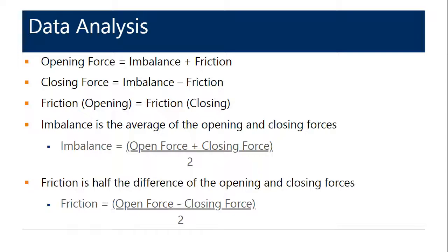Typically, there are other trunnion bascule bridges that have rolling element bearings that support the trunnions that also have low friction. But in addition to the low friction, the rolling lift bridge relies on the fundamental rolling of the curved tread over the flat treads, and they're usually in different segments. So you may have a flat tread where you're rolling uphill, and then the next segment where you're rolling downhill, so the behavior of a rolling lift bridge can feel variable because it in fact is physically different as the structure is rolling back.